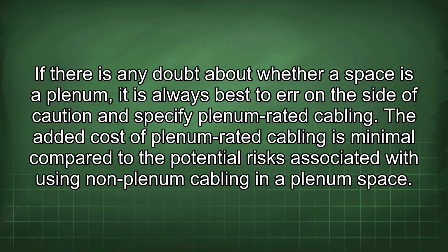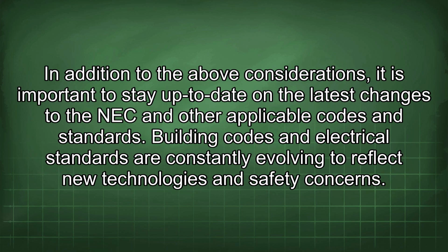If there is any doubt about whether a space is a plenum, it is always best to err on the side of caution and specify plenum-rated cabling. The added cost of plenum-rated cabling is minimal compared to the potential risks associated with using non-plenum cabling in a plenum space. In addition to the above considerations, it is important to stay up to date on the latest changes